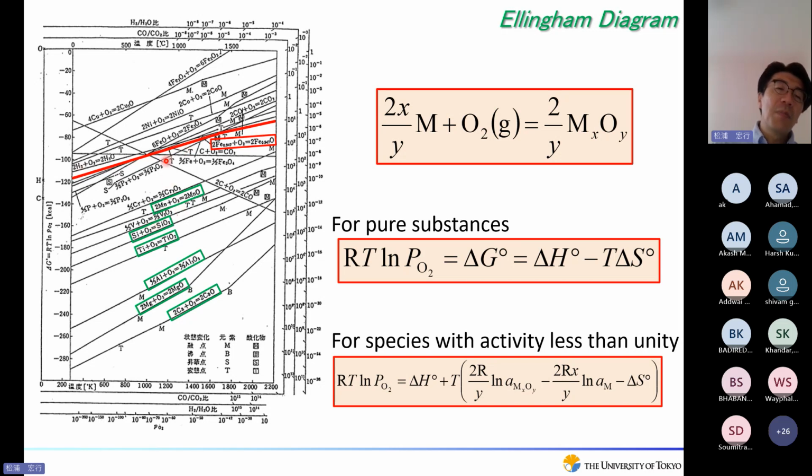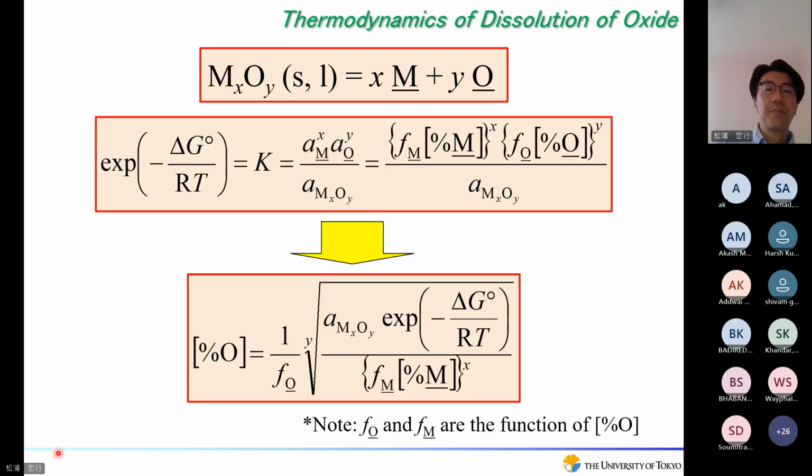The typical deoxidation metals like manganese, silicon, titanium, aluminum, can be seen here. And then you can easily understand that manganese or silicon are moderately reactive elements to oxygen. If you add aluminum or magnesium, these are very strong deoxidizers. And then depending on the steel products, you need to choose among those.